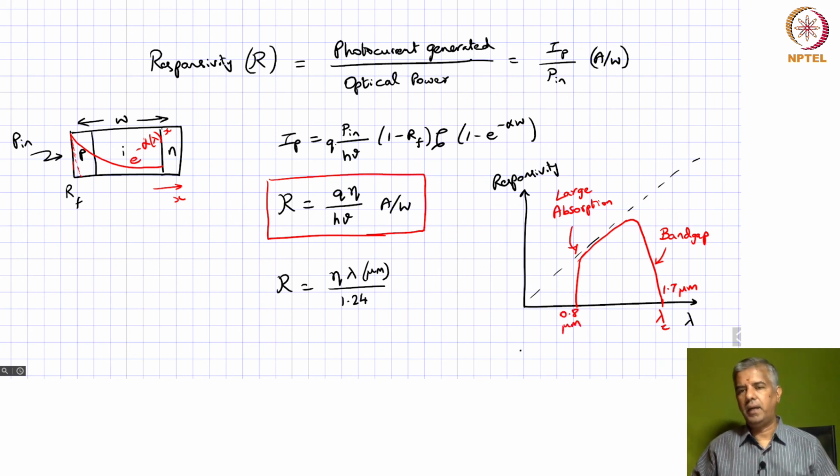So this is for indium gallium arsenide. All these wavelengths are in the near infrared. So for near infrared sensors, indium gallium arsenide is a very good material, and so it is for communication applications where the detection is typically happening around 1.5 microns. Indium gallium arsenide is very good.